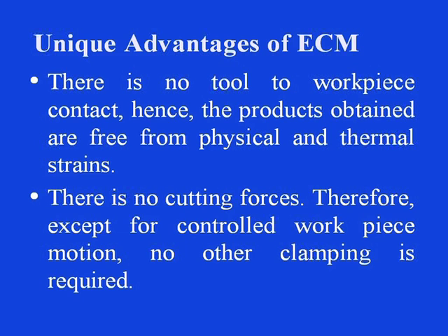Now, let us look into the unique advantages of the electrochemical machining process. As we have said earlier, there is no tool to workpiece contact, no physical contact, hence the products obtained are free from physical and thermal strains. There are no cutting forces, therefore, except for controlled workpiece motion, no other clamping is required.